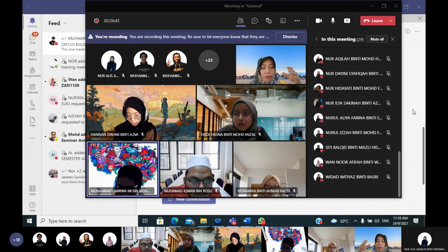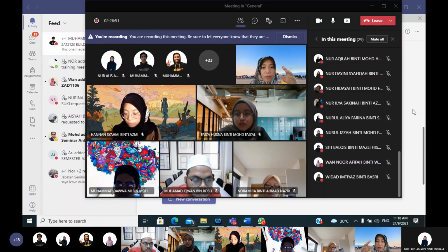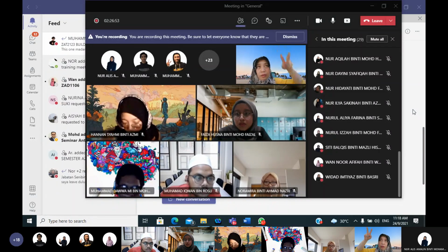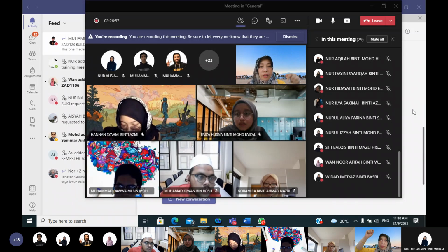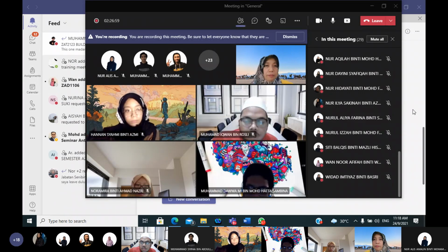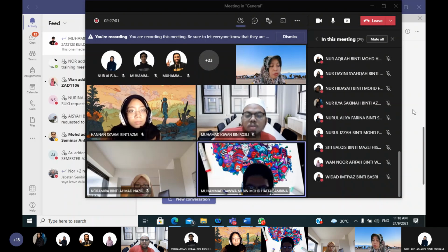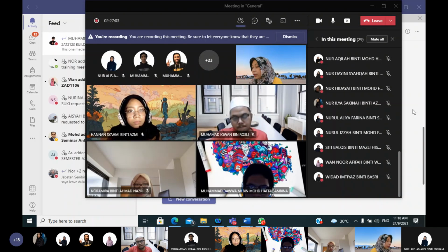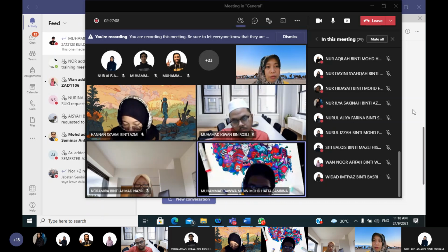You have to refer to schedule 7, apa tu? Schedule 7, travel distance. That is why you need to see the row kat situ, unsprinkled or sprinkled. So if you see that the building is sprinkled, so this is based on schedule 10, then you consider that your building is sprinklered.